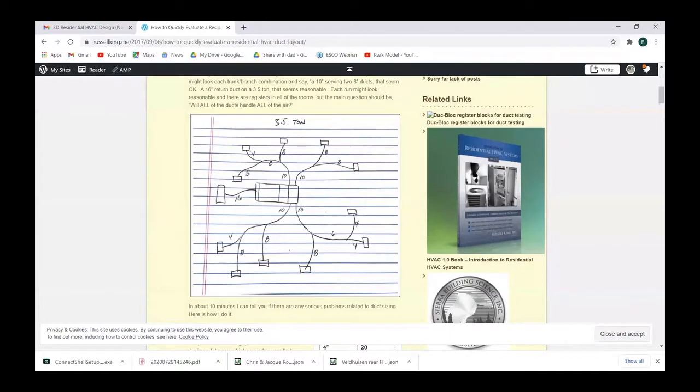Oh, my bad. Also, someone's saying it's interesting that a 2x4 R13 in Rightsuite has a framing fraction of 0.25 as opposed to EnergyGauge, which has a 0.15. So if it has a 0.25, it's a different spacing between the framing. It would be 24-inch on center framing instead of 16-inch on center. That's what changes the framing factor, the spacing of the studs between each other. So I'm not sure, you might want to double check that.